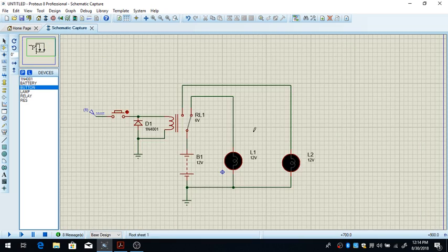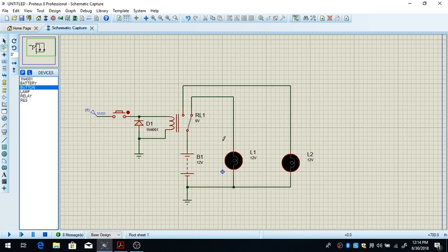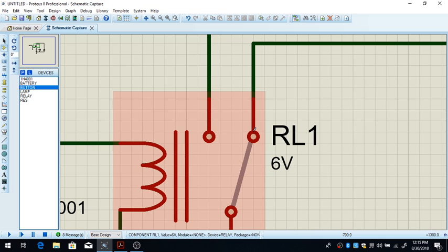So you remember when we had this circuit, in the sixth lecture, when the coil is energized, when the current goes through, and if there is a good amount of voltage here, then this relay, where here we have a ferromagnetic material, is going to switch this node. This one is going to be an open circuit, and this one can be a closed circuit. And when this is switched off, the coil is de-energized and goes back to the first node.